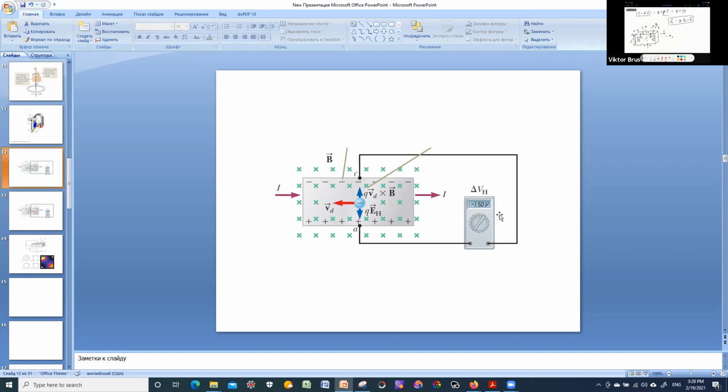N-type semiconductors. N-type semiconductors means that we add some impurities, some doping, into the semiconductor material, single crystal or polycrystalline material, and intentionally increase the concentration of one type of charge carriers. So we can have N-type doping when we increase the concentration of electrons, and then we call them majority charge carriers.